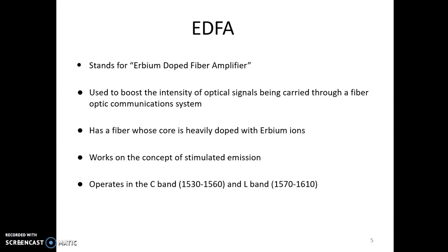In optical communication networks, signals travel through fibers for very large distances without significant attenuation. However, when distances become hundreds of kilometers, it becomes necessary to amplify the signal during transit. Optical fiber amplifiers provide inline amplification of optical signals by effecting stimulated emission of photons by rare earth ions implanted in the core of the optical fiber. Erbium, Er3+, is a preferred rare earth for this purpose. This EDFA operates in the C band and the L band.